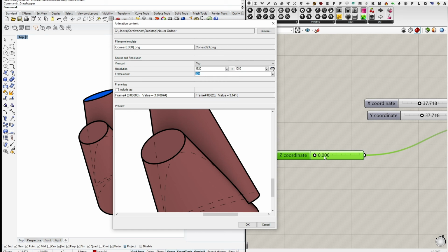So in our case, it would actually always generate the same frame twice. If you have values behind the comma, but just let's say one value, it might find a different slider position for each frame, but it might look very rugged or chopped off because it will sometimes move very fast and sometimes very slow within the animation. So for animating sliders, always add a few commas behind if you want to have more frames, so that you will always receive a smooth animation and not something chopped off.